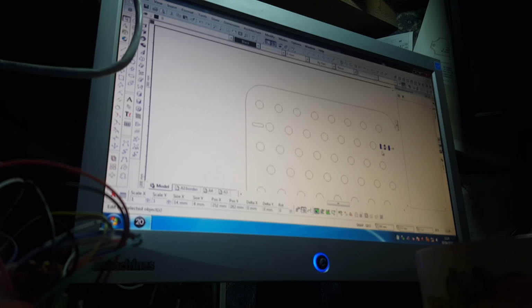Freehand move, but I press the shift key down, let me do that again. So I pick it up on the default, but I hold the shift key down. It allows it to only move orthogonally up or down. So I know I'm going to stay on that center line.